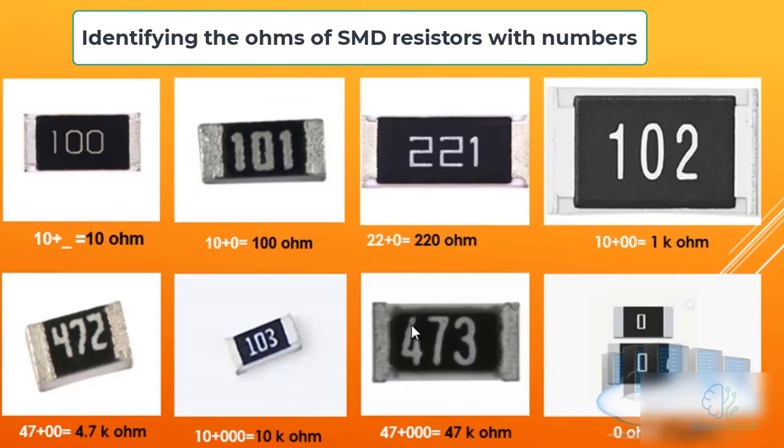In the same way, for any number you see on carbon resistors, those that have numbers, it works like this. Carbon resistors are available both in numerical form and as a combination of letters and numbers, which we will learn about and discuss more in detail later. Those that are numerical are this simple and very easy to calculate, so the last number you always consider as the number of zeros. But the first and second numbers are always their own values. For example, here 47 is just 47 and this number 3 means 3 zeros, which becomes 47,000 ohms or 47 kilo ohms. So it's 47 kilo ohms.